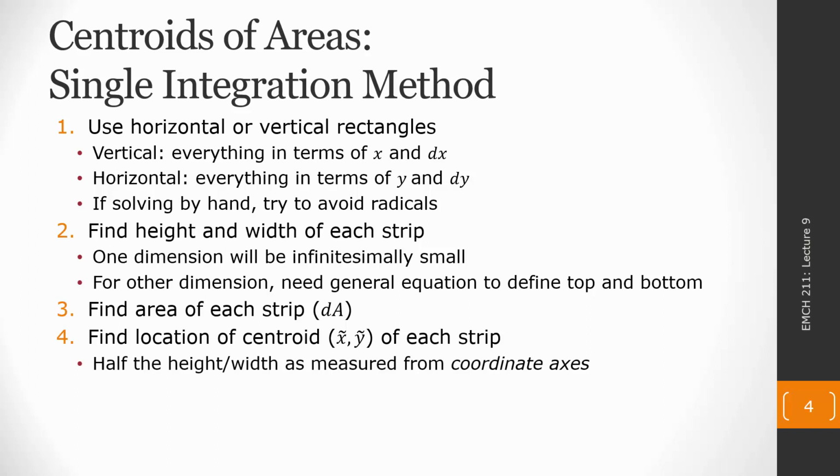We're always going to be measuring this from our common origin for the shape. So every little strip is going to be measured from the same origin. So since we're making every one of these strips as a rectangle, the center of a rectangle is going to be located at half of its height and half of its width. So we want to find out how far is that point for any one of these strips from the origin.